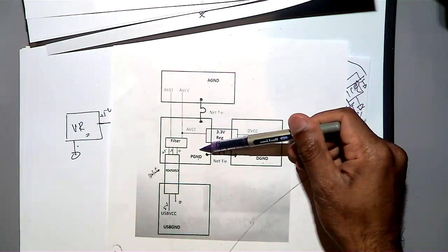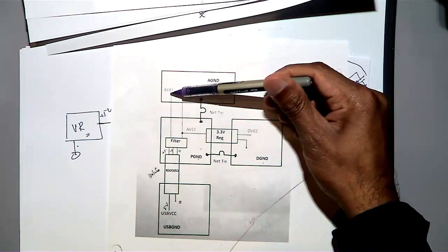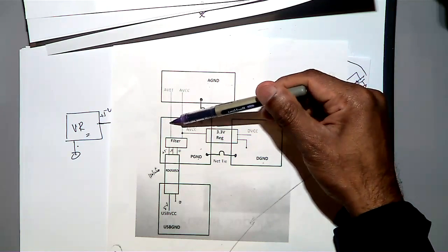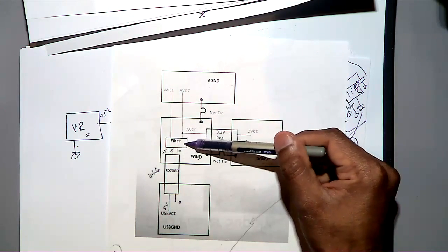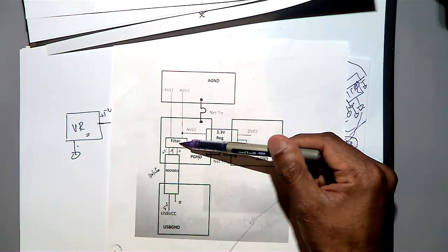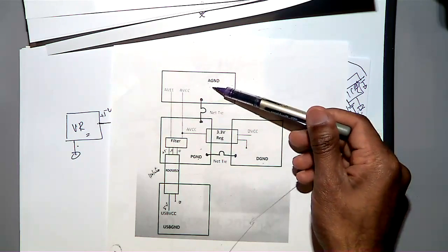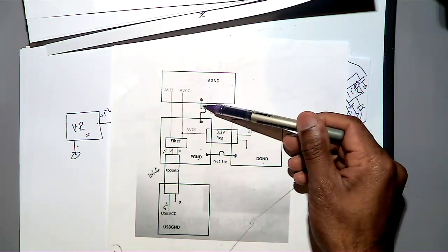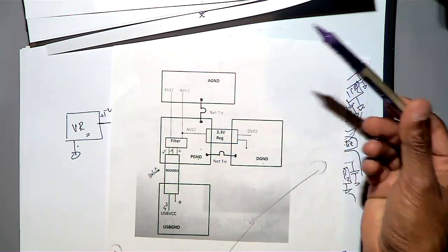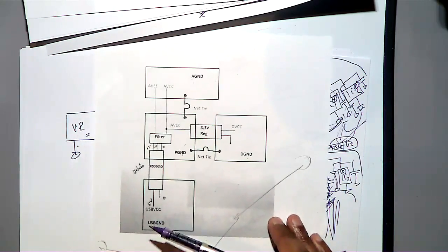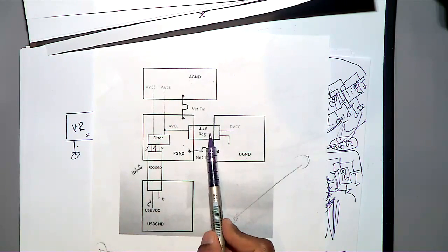When you have these 4 grounds, you can see here your power supply. From the power supply, you can see plus VCC, VW are going on the top, and then we will be using a lot of filters like inductor, capacitor, all these things to avoid the noise. And then the grounds are connected only using one point called a net tie. See, here we have used a net tie. Again here, from the power supply, you got a regulator here, that is 3.3 volt.